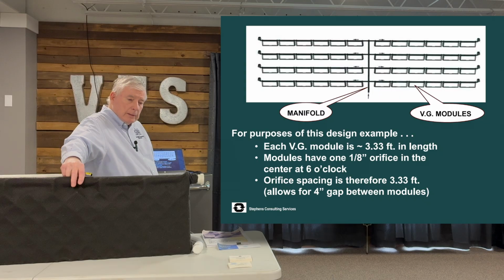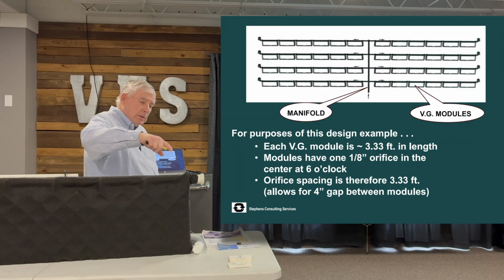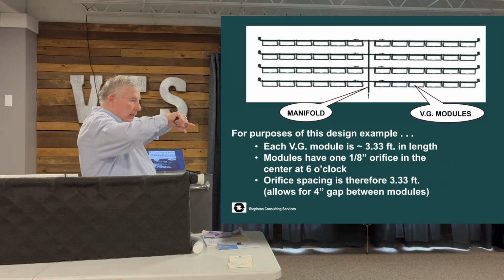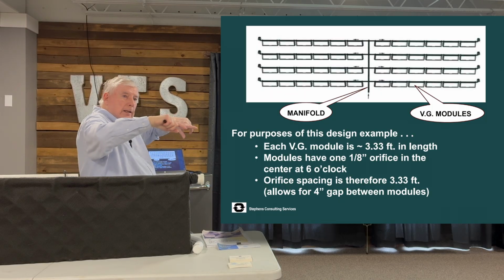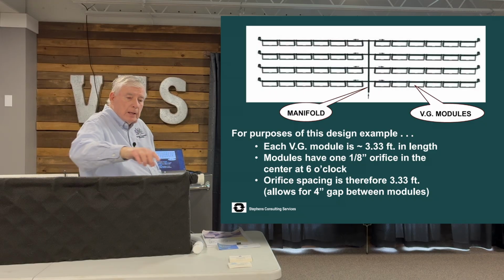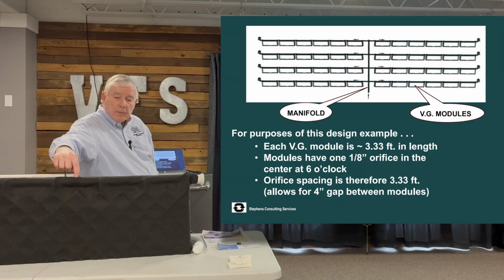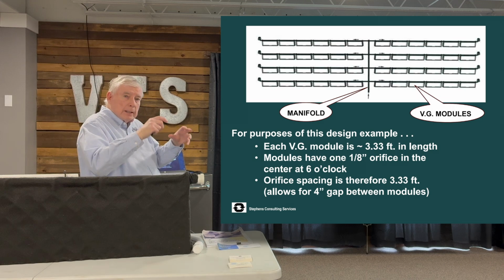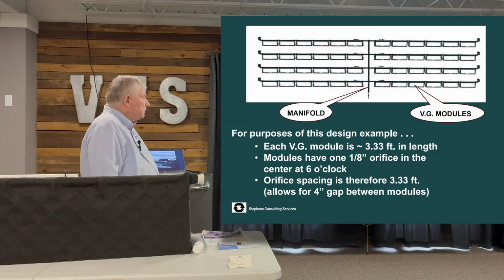These are installed in the vertical direction, but if you messed with them, you can rotate that pipe. It probably, from 4 o'clock to 8 o'clock, has no consequence. But if that gets rotated so the orifice is up against the fabric, it will inhibit the flow coming out of that orifice. So you don't want somebody messing with these and rotating them a lot.